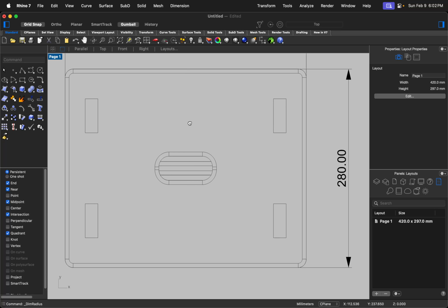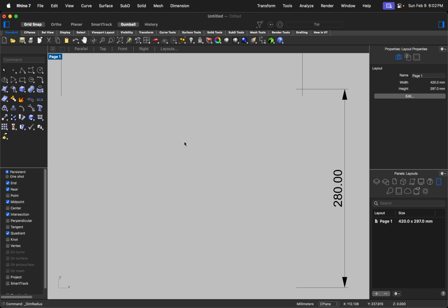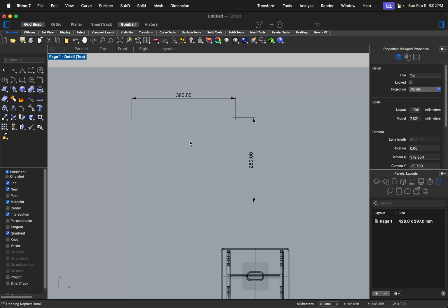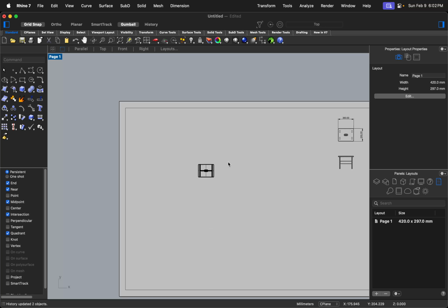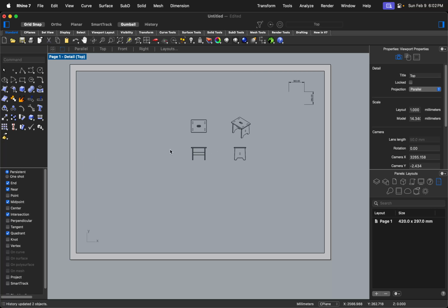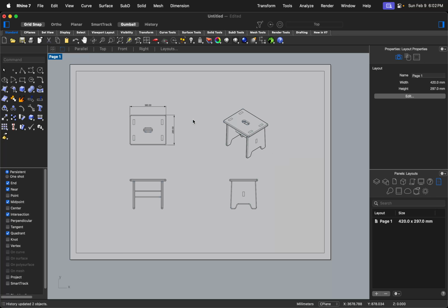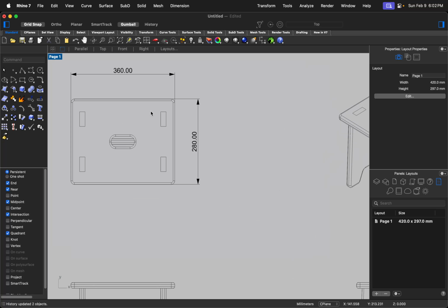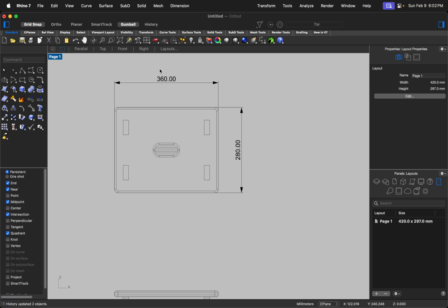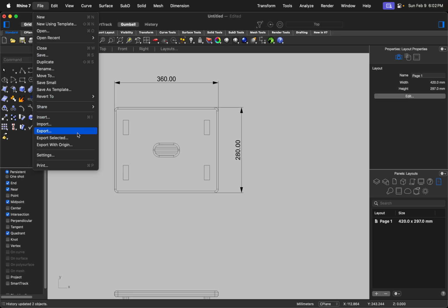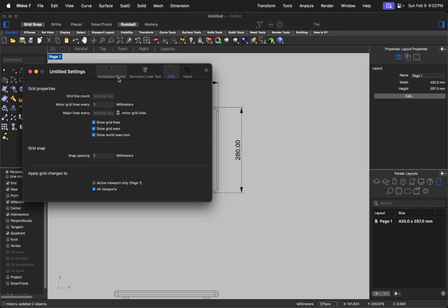Okay, so whenever you have, whoops, what's going on? Why is the dimension interesting? Let's just leave it. Alright, so come back here. Whenever we have a problem with the decimal point, one way to tackle this is to go to the annotation style. Or you can disable the decimal point if you want.